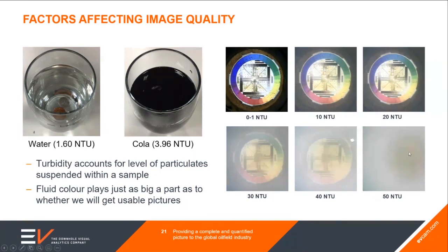The second factor that we have to deal with is suspended solids inside the well fluid. It may be that we've got a nice, clear, pigment-free medium, but there could be suspended particles, fines, dissolved solids, or even that you've got a brine in there. You've weighted it up with a particular mineral to kill the well. And it's those particulates that, again, absorb and scatter the light.